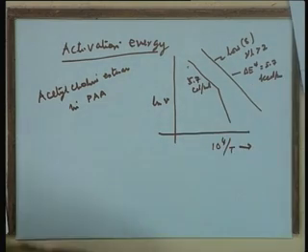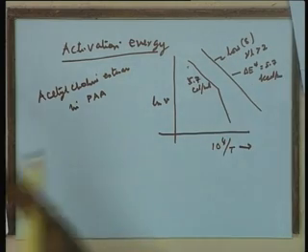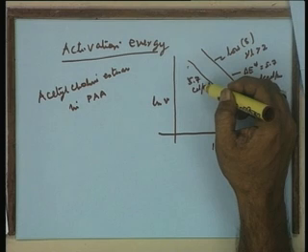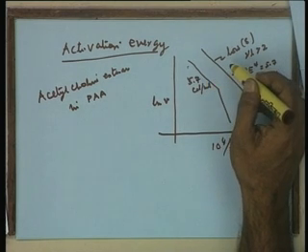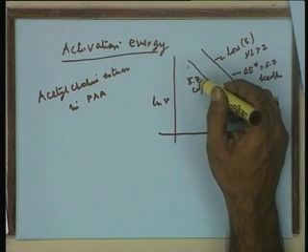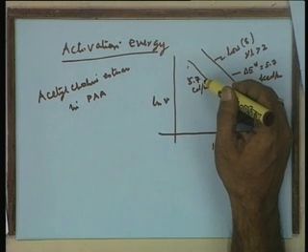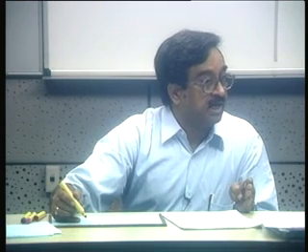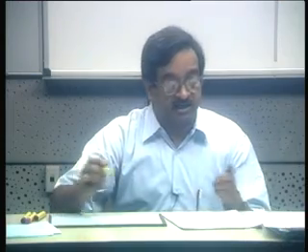Now when you go over to high substrate concentration, over the range of temperature, initially at the high temperature range almost a similar activation energy, 5.7, was obtained. That means the system behaved almost like a diffusion limited one, even at high substrate concentration, which it should not. But because at higher temperatures the reaction rate is higher, the diffusional limitation was established.